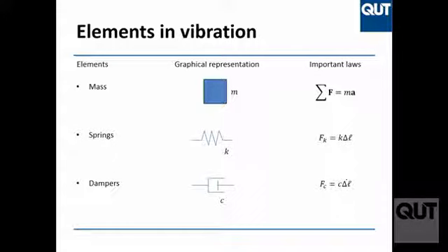This is an example in which vibration is used as a symptom of something else that goes wrong. In that case, it's not that vibration is so bad. You get a bit of massage while you're driving. It's not too bad, but you know that there's something wrong. So vibration is also used a lot for condition monitoring. Vibration is very often a symptom that there is something wrong in the system.